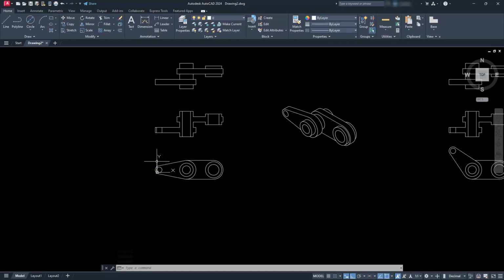And let's go ahead and create a title block, right? So I'm going to decide which way we're going to go about this. When we've got multiple sheets and multiple views and things of that nature, this is when AutoCAD using paper space really will excel, right? So I'm going to use paper space in this just because I have multiple iterations of sheets. Now I can do this by using multiple drawing sheets, but you're going to have a bunch of different sheets up here, and they're going to be actual different CAD files. So the best thing for AutoCAD, if you're trying to keep everything in one file, is to use paper space, and you can have multiple sheets all attached to one drawing.